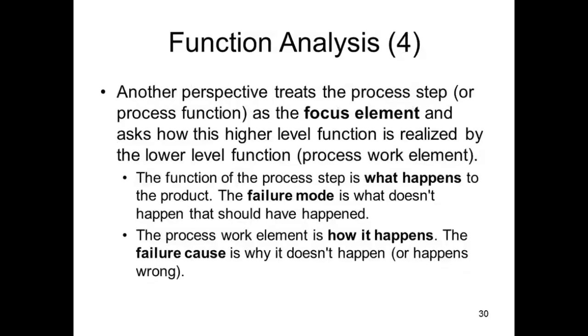Another perspective treats the process step or process function as the focus element, and asks how this higher level function is realized by the lower level function, the process work element. The function of the process step is what happens to the product. The failure mode is what doesn't happen that should have happened. The process work element is how it happens. The failure cause is why it doesn't happen.